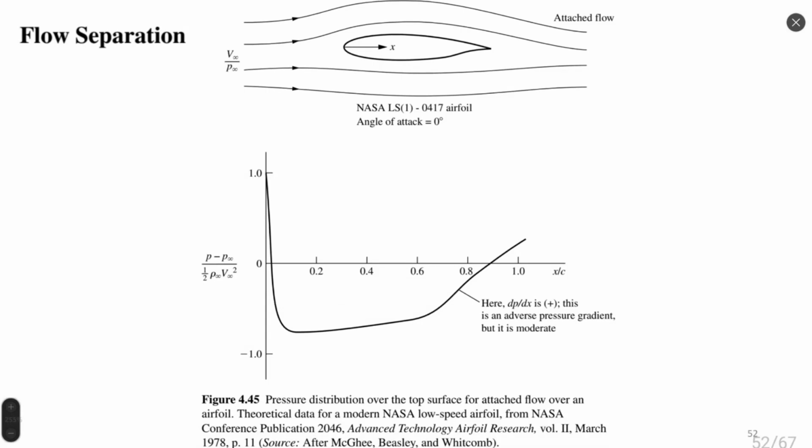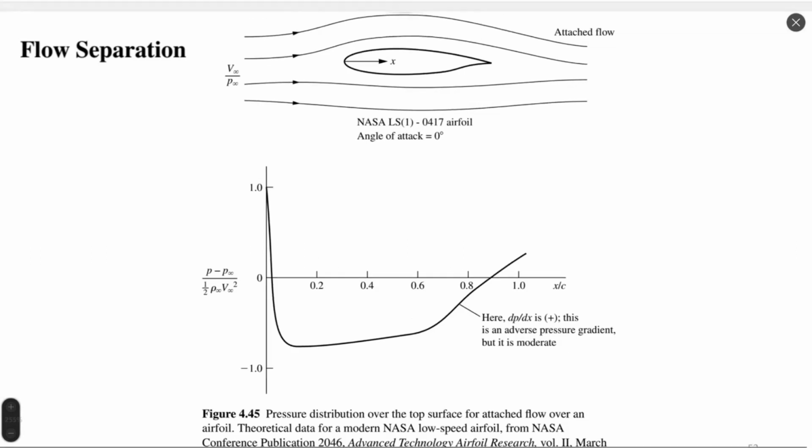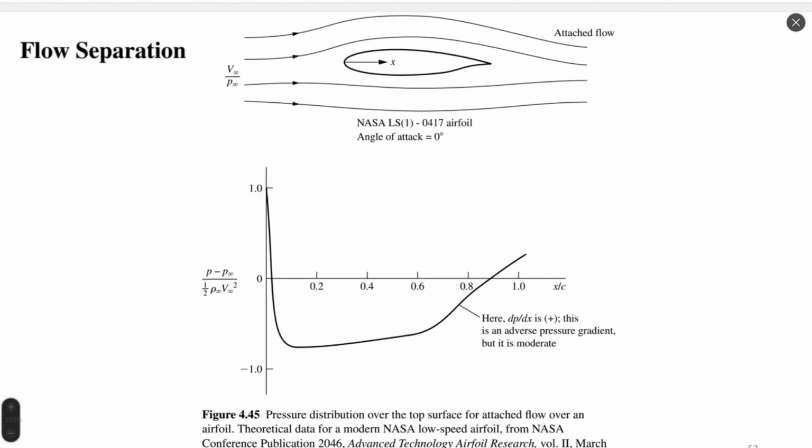Flow separation is another concept which Anderson takes into account. This flow separation is strictly related to viscosity. Flow separation can be seen not just on flow lines, but also on the distribution of pressure coefficient. Flow separation happens originally at a region with negative pressure coefficient, and it happens because of pressure gradient.